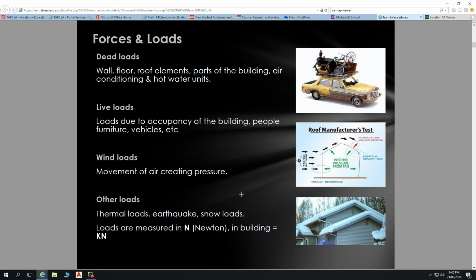So you install it by stretching around, pulling it with the claw hammer, stretching it, nailing it off with the other hammer or your nail gun, whatever, and then you put tension in your bracing to tension that up, so that when the wind pushes on the side of the building, with a pushing force in this fashion, this piece of bracing becomes activated. A pushing force in this direction, this piece of bracing becomes activated as the wind tries to elongate that rectangle in that fashion. So you've got strap bracing like this.